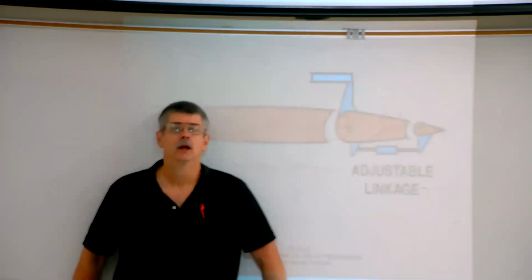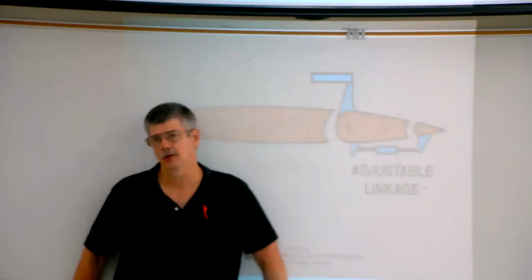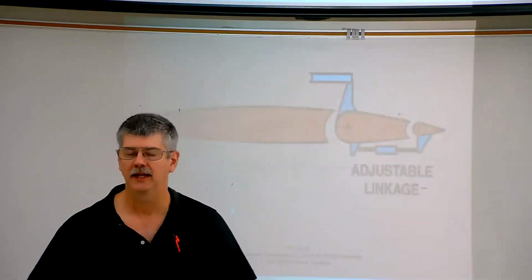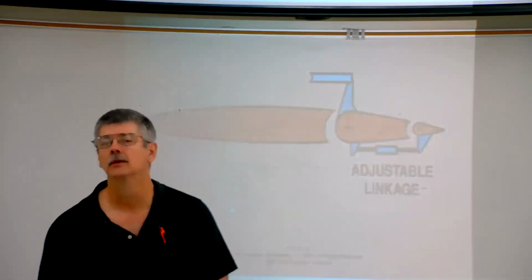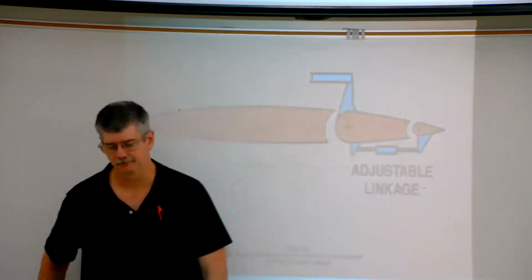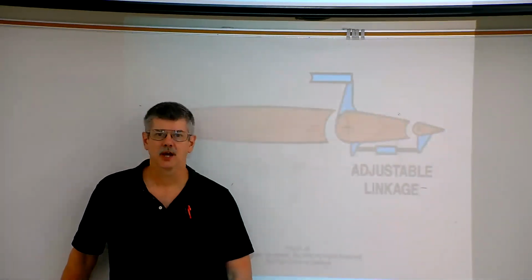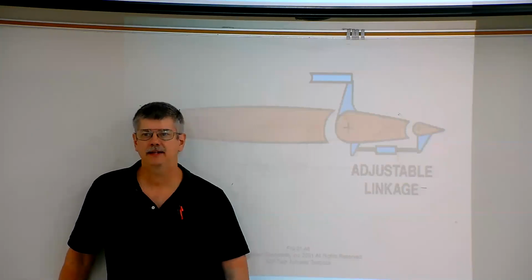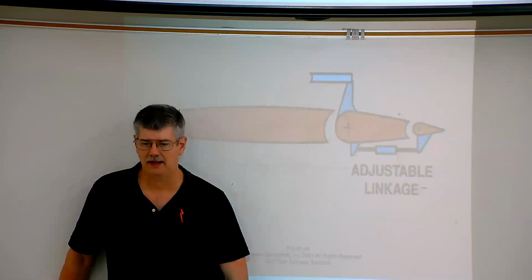A servo tab aids the pilot in movement of the control. Now, because they're both tabs, they kind of do the same thing, but they are slightly different. Some tabs can do both, and that is help trim the aircraft and also act as a servo tab. If a tab has both functions, trim and servo, then it's known as a balance tab.